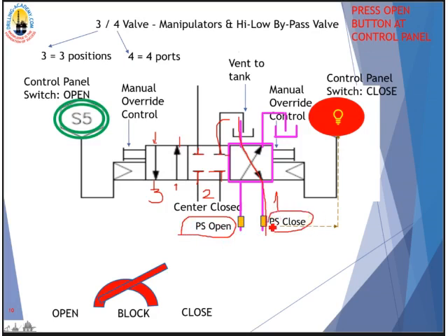And the pressure switch, upon sensing the pressure in the line, will send the electric signal to light up the light bulb in the control panel. In the old days, they didn't use a pressure switch, but they used a proximity sensor to sense the position of the valve. But that's the old days. Now, modern day, they use a pressure sensor, which is more compact, more cost-saving, and more precise.